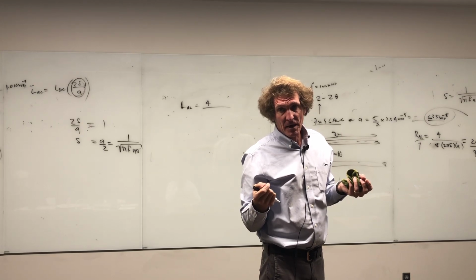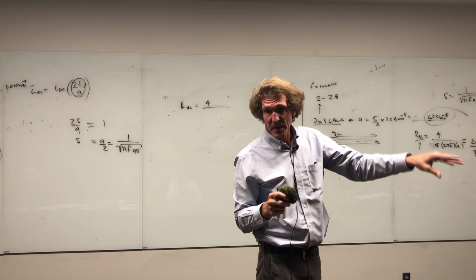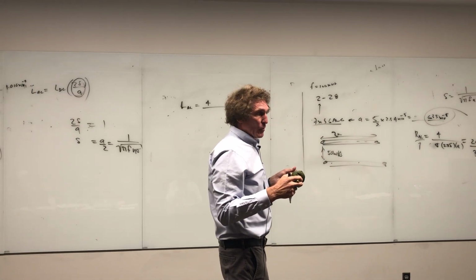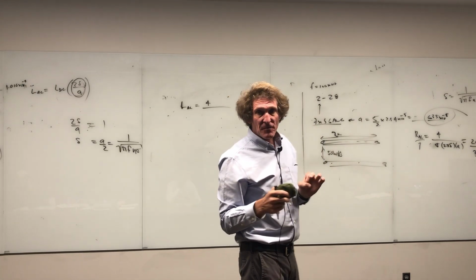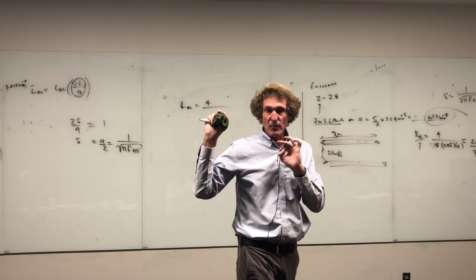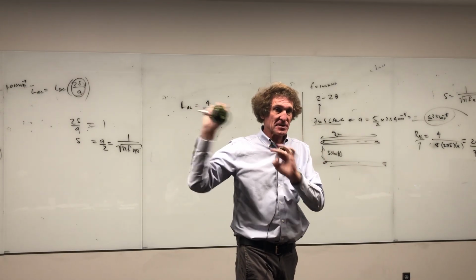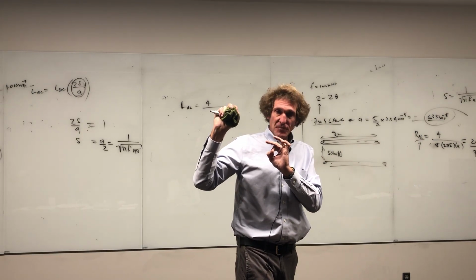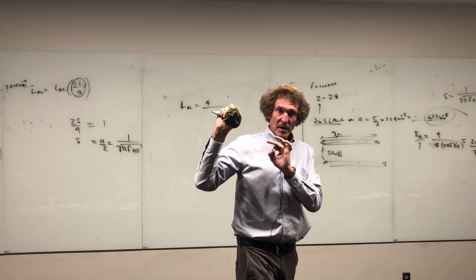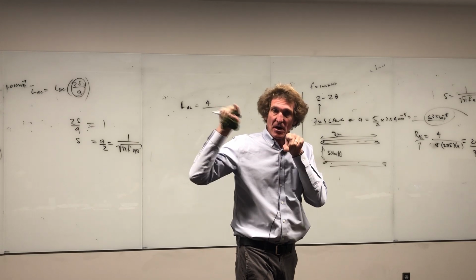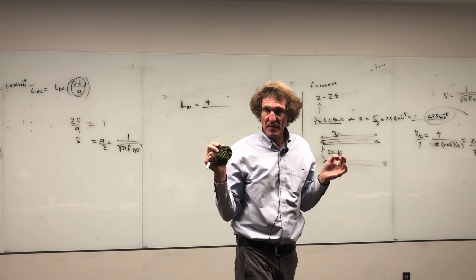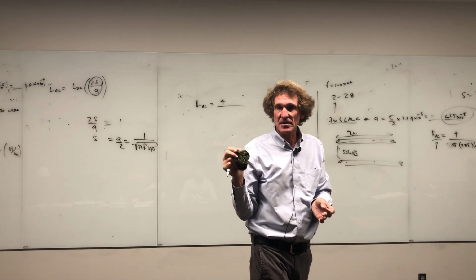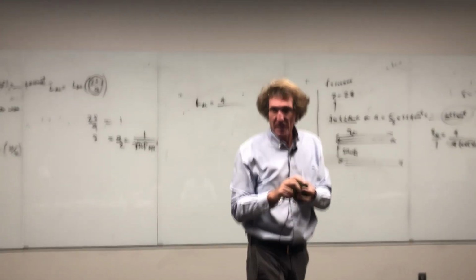But I don't want to get too far afield from the basic problem. Yeah, I just was wondering if there was more than 2 wires. Well, whenever there's power delivered or signal delivered, it's a differential. There's a plus minus voltage that drives the actual transmission line, if you will. We don't ever send information by common mode. We just don't do that. As a matter of fact, common mode is to be avoided at all costs because it's usually very destructive. And we'll get more into that later.